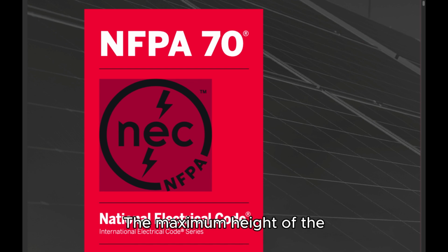The maximum height of the working space shall be the height necessary to install the equipment in the limited space. A horizontal ceiling structural member or access panel shall be permitted in this space. 5. Separation from high voltage equipment. Where switches, cutouts, or other equipment operating at 1000 volts, nominal, or less are installed in a vault, room, or enclosure where there are exposed live parts or exposed wiring operating over 1000 volts, nominal, the high voltage equipment shall be effectively separated from the space occupied by the low voltage equipment by a suitable partition, fence, or screen.